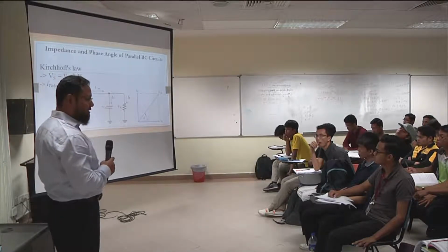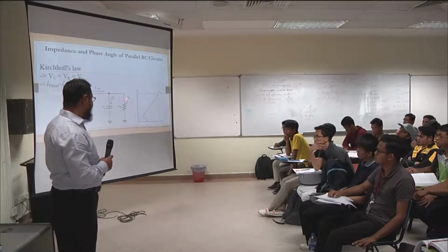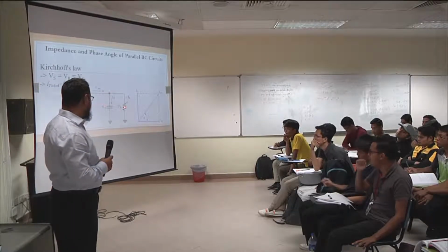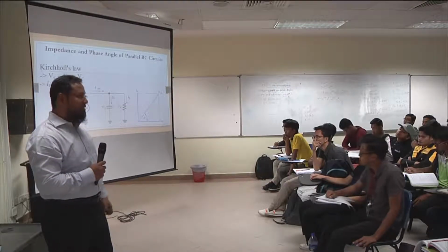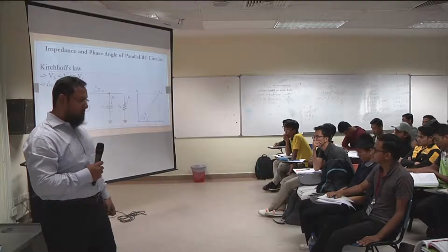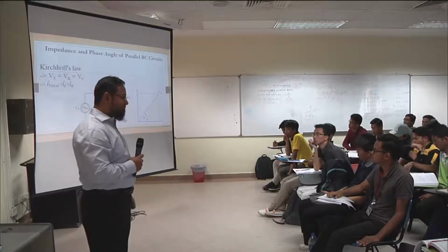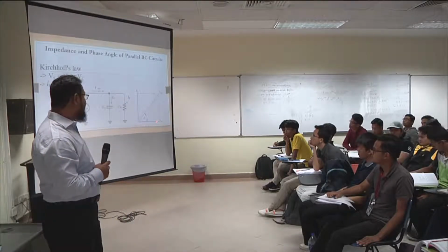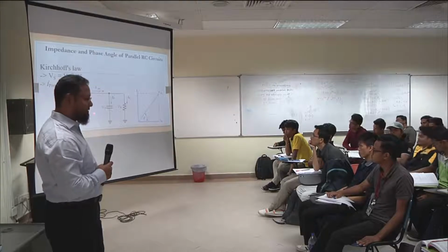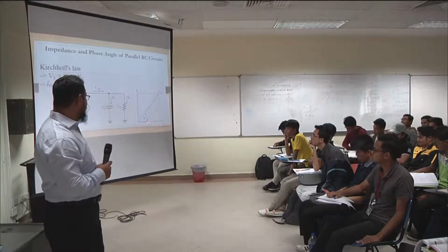The whole voltage across R is Vs now. So IR is going to be equal to Vs divided by R. Let's say Vs is a phasor. R is also a phasor, but with 0 angle. So that's not going to change the angle, which means IR will be in phase with Vs. Okay? So let's put it at 0 angle.